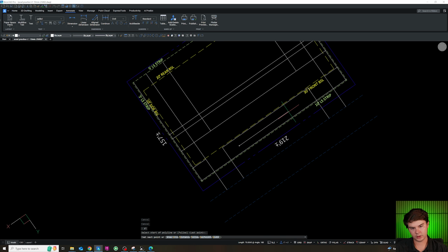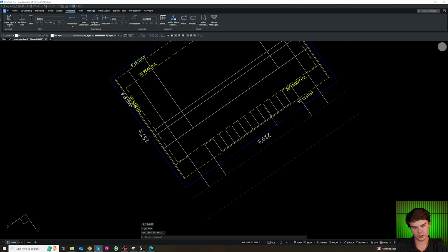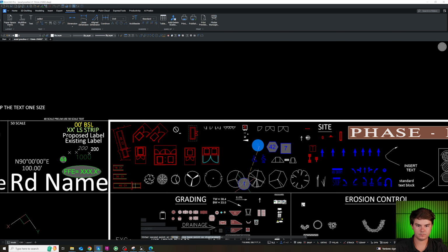Use the join command, J. Now these are all joined and connected to the main road. We will put in our spaces by offsetting 9 feet and click M for multiple, and then you can just click all the way down. Make sure to delete overlapping lines, those get in the way. Now we have our 11 spaces, we will mark that with a spot.